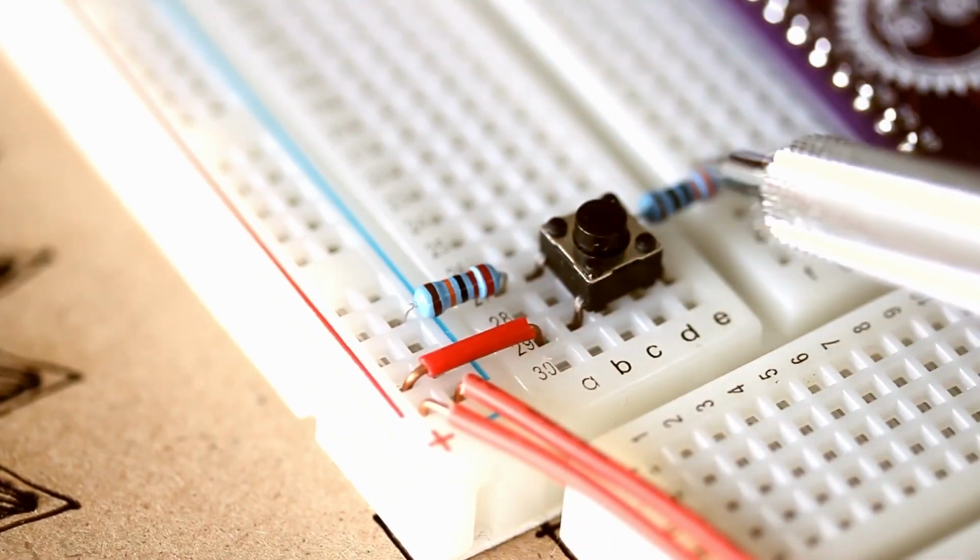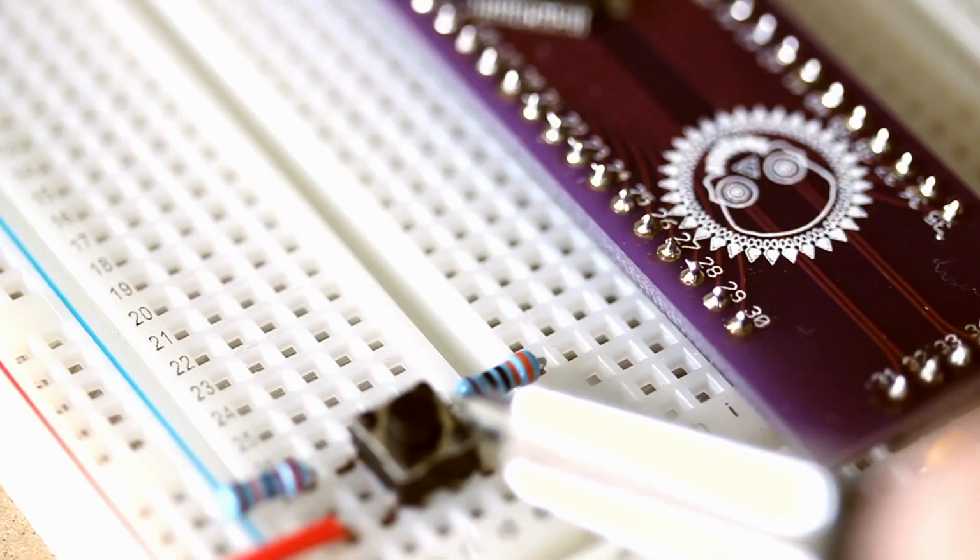And it'll also be connected back to pin number 27 with the 330 ohm resistor. We're going to be looking at the GPIO input registers, or the registers we need to use to make the input happen. The registers that we use for the input are very similar to the registers we're going to use for the output. In fact, some of them are the same.